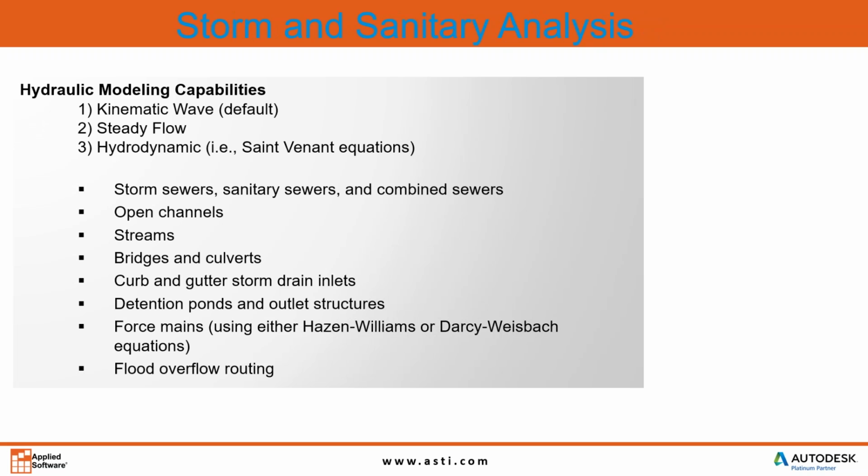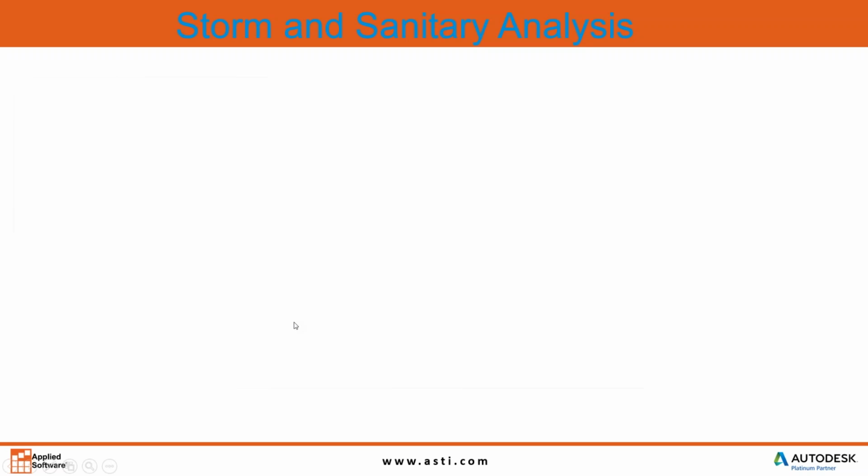So one of the things you look at, because most people say, well, I have hydroflow, why can't I just use hydroflow sometimes? And hydroflow does kinematic wave and steady flow. Storm and sanitary analysis also does kinematic wave and steady flow, but also does hydrodynamic. So storm sewers, combined sewers, open channel streams, bridges, culverts, detention ponds, force mains, and then overflow routing.